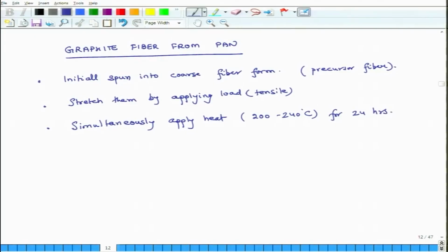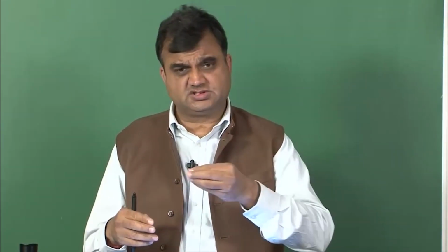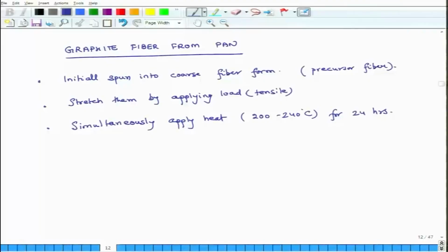Okay. So, you are applying some external force and you are applying heat, and in this heated state things soften up and the carbon atoms and molecules in the fibers get to align at elevated heat because things start flowing. Okay. So, you apply heat, and this is in an oxidizing atmosphere. So, whatever volatiles are there and things which will burn off easily, they burn off, but carbon will not burn off easily because you have to heat it at a higher temperature beyond 250.